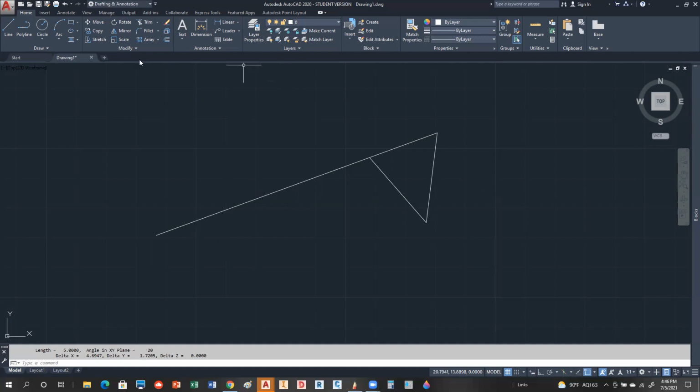But if I do this in AutoCAD, I can say, okay, scale this. Here's your base point. And I want you to scale it by 1/12. So you type 1/12, and it did the math for me. It floated it out 14 sig figs. That's a much better way of doing it, especially if you have a fractional number that's not going to be a great fractional number. Okay, so that's the scale command.